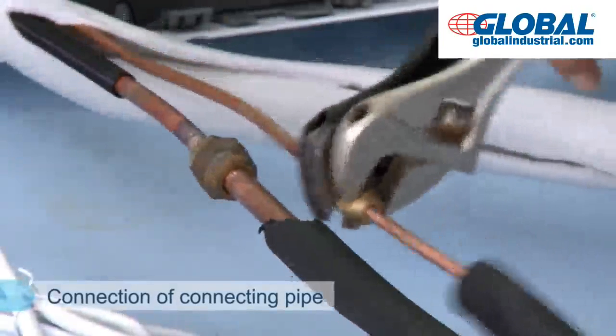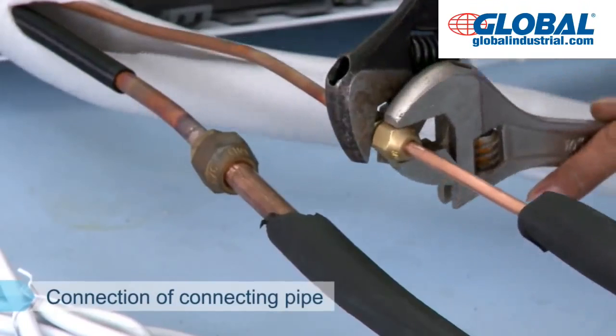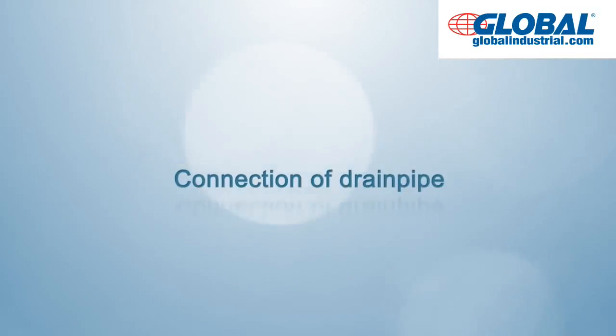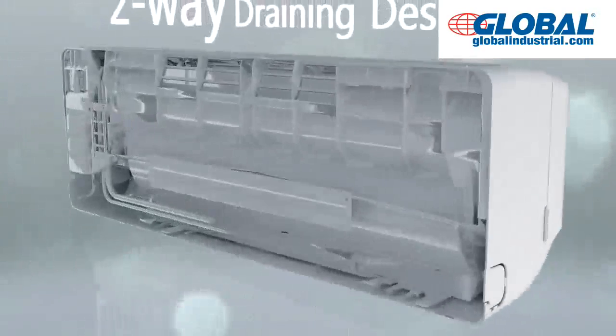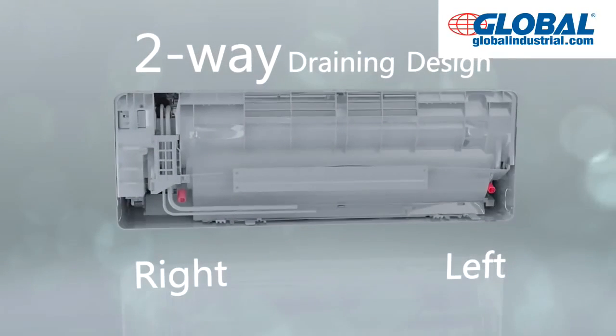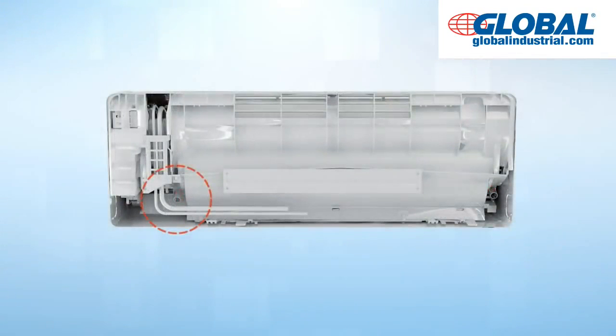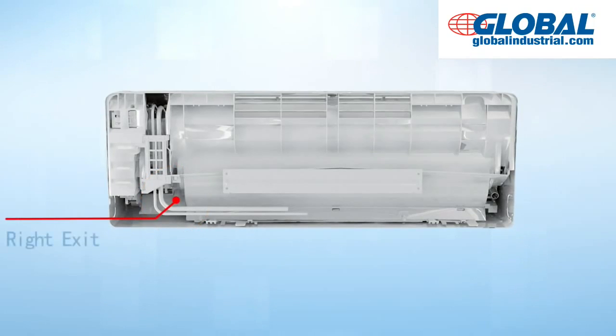Firstly, connect low pressure pipe, then connect high pressure pipe. Connection of drain pipe. This series of product is featured by two-way drainage function, and the position of drain pipe interface can be selected according to installation position. Note that during the adjustment of drain pipe, unused interfaces should be sealed by rubber plug.